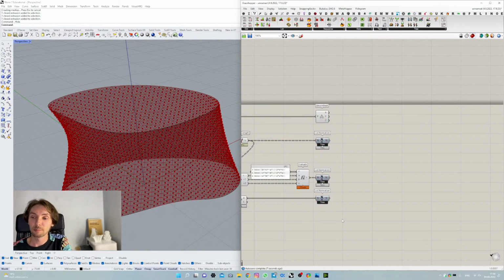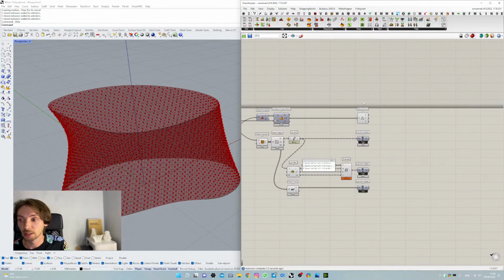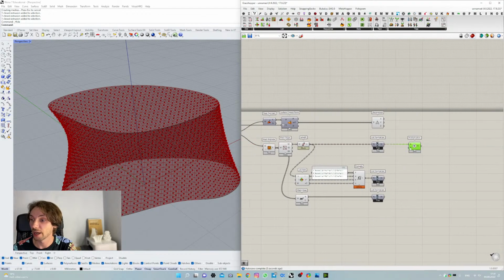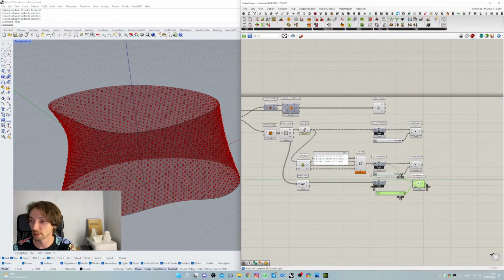And again, we can provide different weight for different parameters for clusterization. I'm unitizing and normalizing the data in order to multiply it later. So let's say I have a list normalizer for the edge length, and I can multiply it by some value. Let's say 1 for now. And I'm going to do it for every parameter I have. So I will have more control on clusterization.